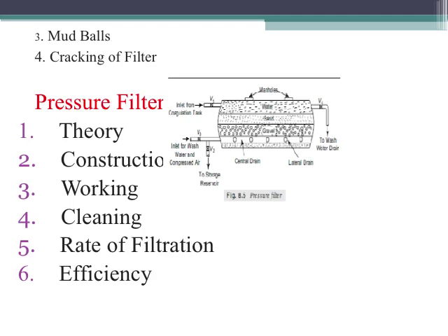The use of the surface wash technique instead of the old conventional backwashing technique has proved to be very successful in eliminating the formation of mud balls. These mud balls may even be removed by breaking them up with rakes or some other equipment and then washing off the particles. It could also be cleaned by washing the filter with a solution of caustic soda or some other such chemicals.